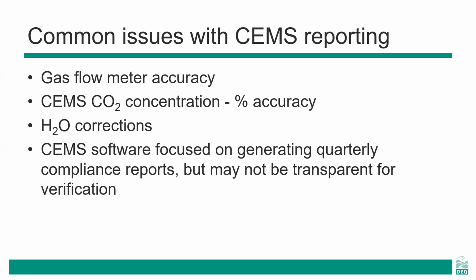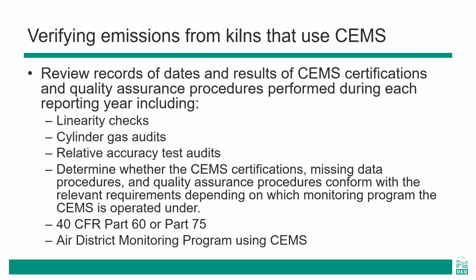There are some common issues with CEMS reporting that verifiers should be aware of. Verifiers should ensure all monitoring and QA/QC requirements described in 40 CFR 98.84 are being followed. Verification of CEMS data was also discussed in Course 2 titled Stationary Sources, General Information, and Stationary Combustion. The verification approach of CEMS data focuses on ensuring the reporter has completed all of the required quality assurance and all of the maintenance requirements for their CEMS equipment.